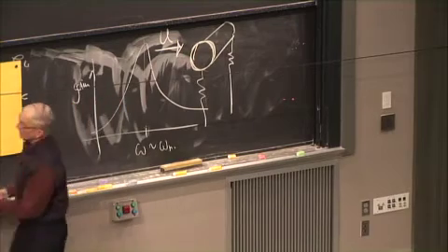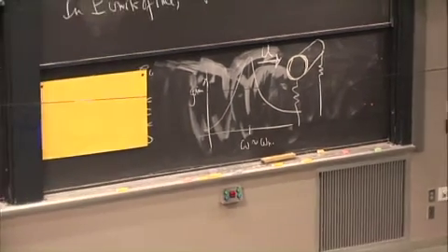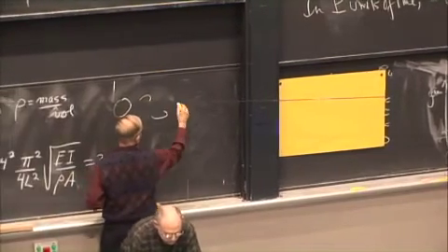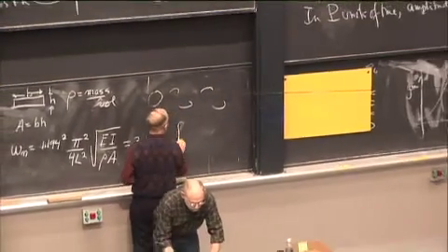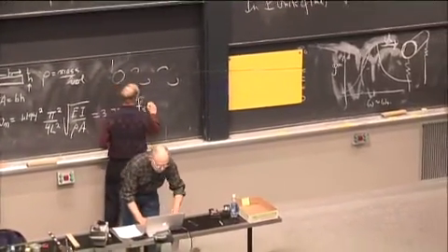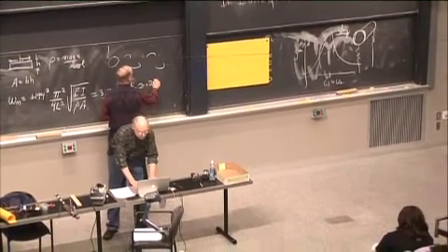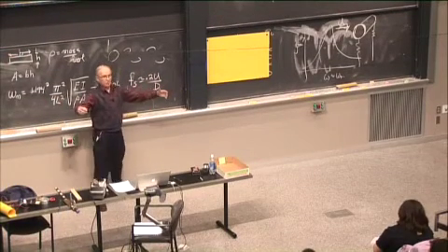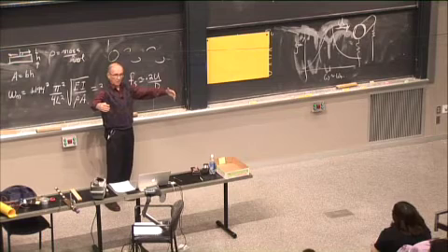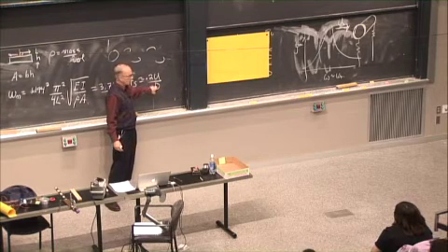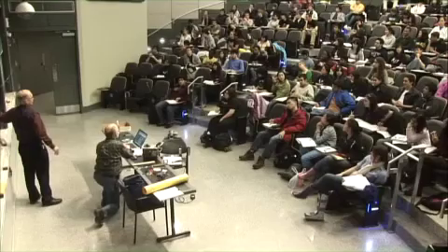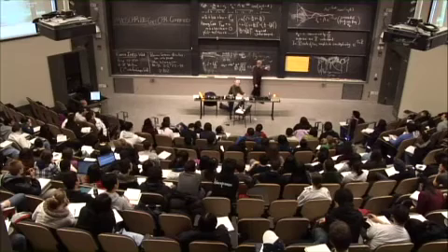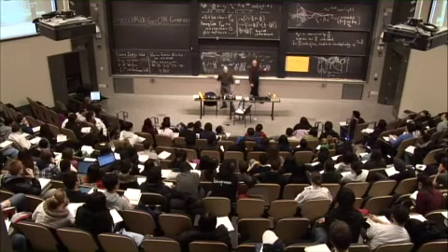in the wake of the cylinder, vortices are shed, little eddies. And the frequency of the vortex shedding is approximately 0.2 times the flow velocity divided by the diameter in any consistent set of units. So I study big things in the ocean. If you're drilling for oil, it's through a thing about 1 meter in diameter. So if D is 1 meter, and 1 meter per second is a common flow velocity of currents in the ocean, about 2 knots. So 1 over 1, so it's about 0.2 hertz.